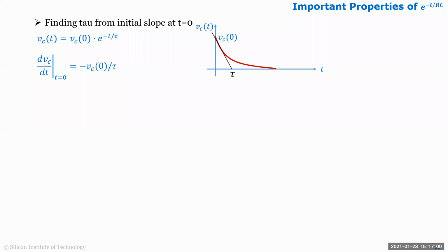So experimentally, let's say you have many poles in the system, but a lot of times you'll see that there is always a dominant pole, right? Let's say you did a step function, and you know there are a lot of poles around, but there's one dominant pole, and you want to know the time constant of that dominant pole. If you do this in an experiment, you'll get your dominant pole. Okay.